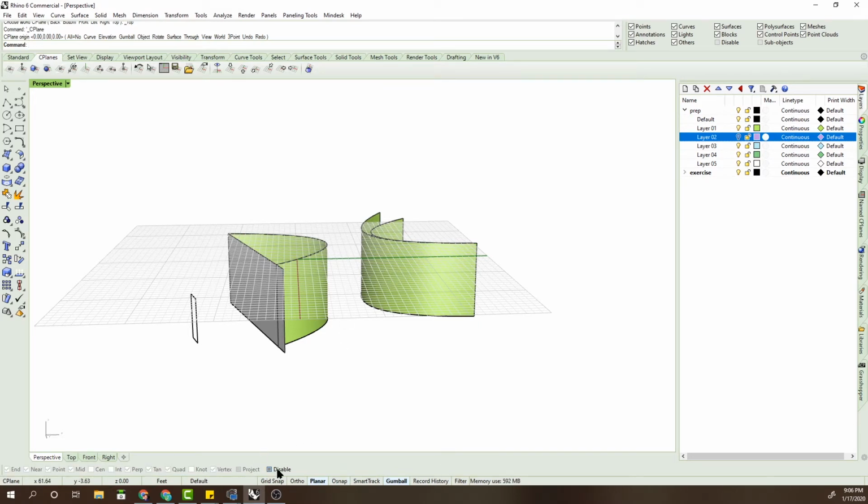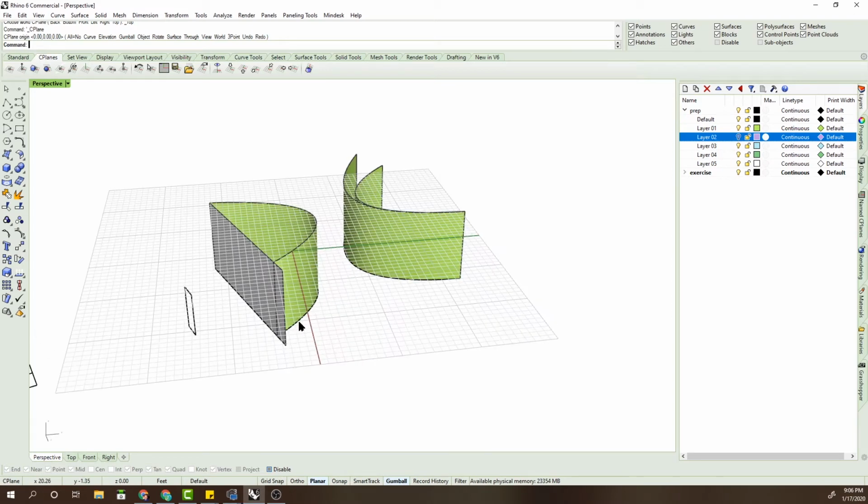The benefit with disabling it is you can, let's type a line. Up here, let's select tangent, and then I'm going to click here, and if I hold Alt, you can see now down here, this is temporarily available, making the snaps available.